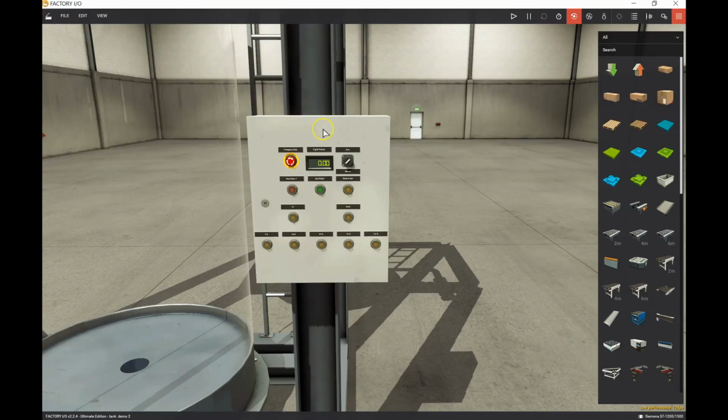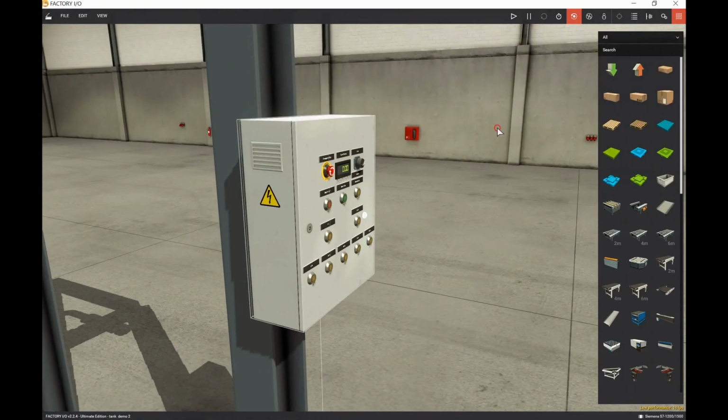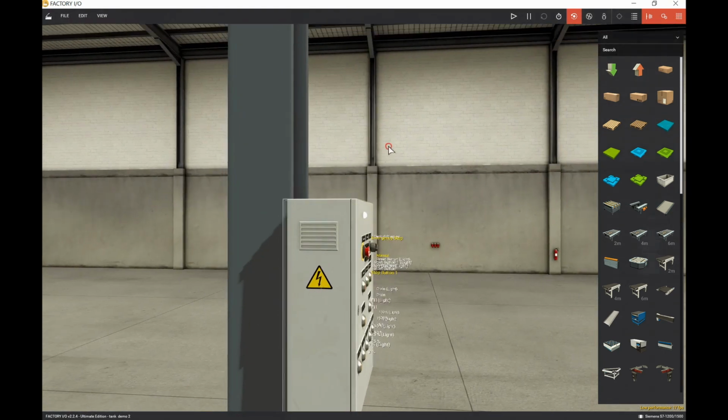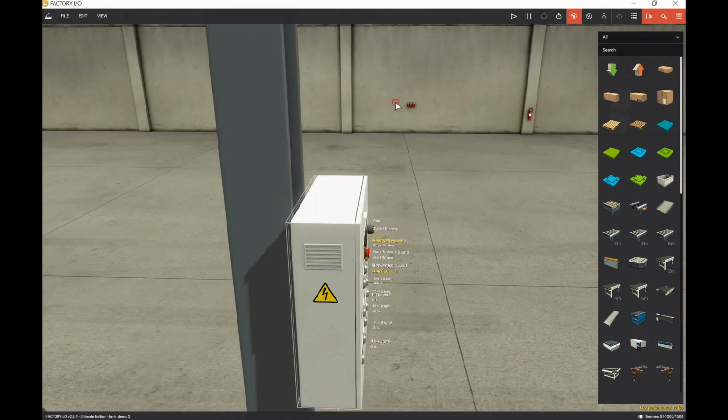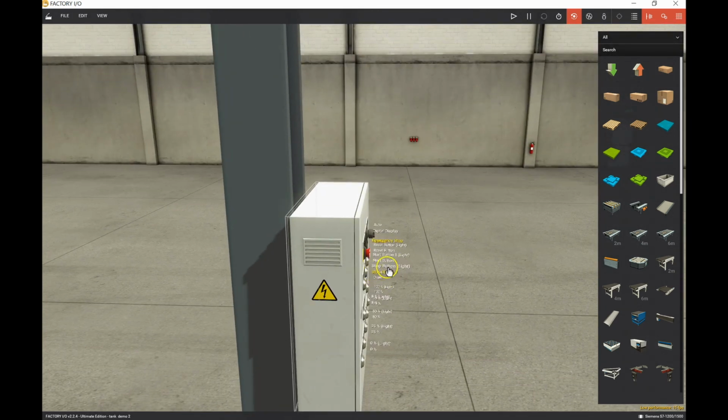If we go back here to our animation and we look at our box here from the side, and I dock these guys, meaning I show my sensor tags. So those are all my discrete inputs, being my stop, start, reset, and auto, manual, emergency stop, fill, drain, and each of the different inputs here. Now, some of these guys have indicator lights that go with them. So if I come here and dock my actuator tags, you can just make it out that the stop push button has a stop button light and the start button has a start button light there.